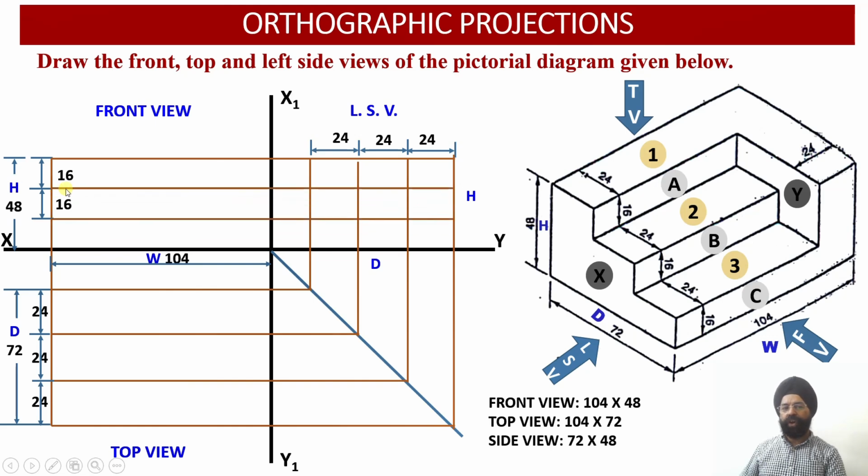So I am going to draw, please check, 2 horizontal projection lines through these points, where I had identified that these are the heights of the element number 1, which is A, and the element number 2, which is B. So I have got the basic construction completed over there.